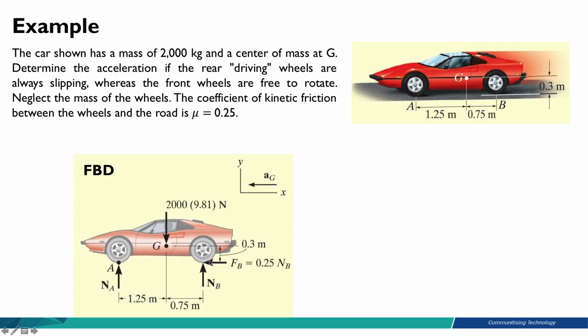The direction that you point the friction force here does not really matter, because if you point the friction to the right, then in the end, in your calculation, you will get a negative value, which means that the direction is actually pointing in the opposite direction. So this completes the free body diagram of the car. So we have in total 4 external forces acting on the car. Remember, apart from the free body diagram, you also need to draw the kinetic diagram.